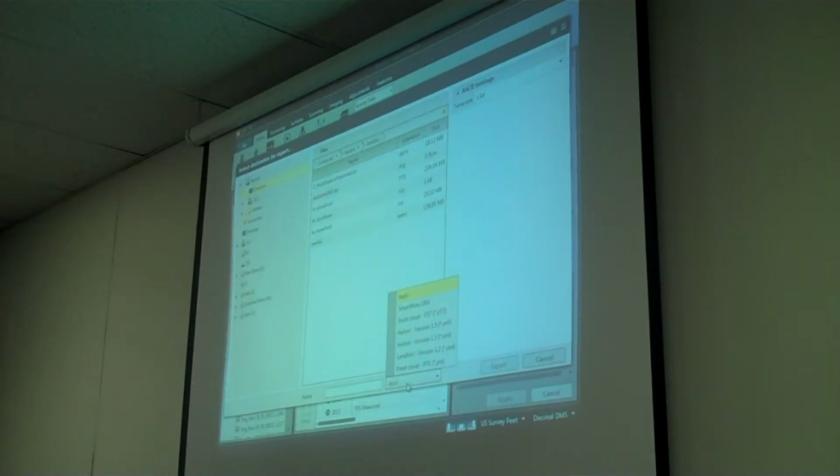So when you guys were talking earlier about the scanning capability, it's all about, you got to start with the end in mind, right? How dense of a scan do I need? What are they going to use this data for? As I've collected all these points, this line work, how do I want to share this out with people in my office? So if I was going to Revit with a point cloud, I might use this PTS file format.